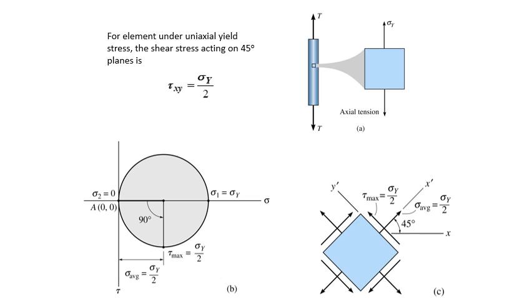So if we draw the Mohr circle, we'll find that we have sigma 1 on the right and sigma 2 is 0 because the stress element does not have stresses on this plane. Now you might ask, why is it normally called sigma x, but you can also call it sigma y, depending on the direction in which this element is drawn.